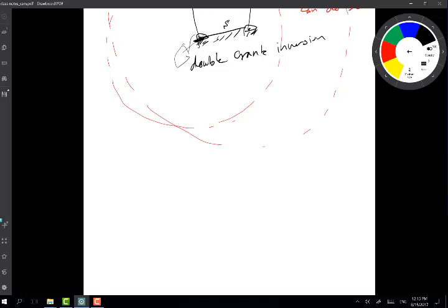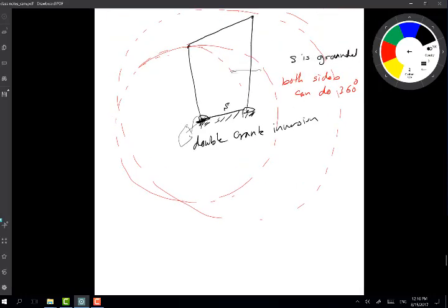You'll have rocking motion, all that sort of thing. And also non-Grashof linkage does have its own application as well, right? So just like wiping, you need this rocking motion for some application, and you drive it with a servo motor that does a certain angle in each direction, so it doesn't do continuous rotation, but it does also exist.